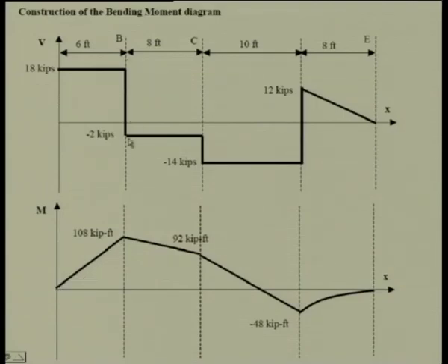Then suddenly it goes down, it is minus 2 kips. So, as you can see here, it is the sum total. So, it will keep going down after that. Once it reaches the maximum here, you are putting the moments, you are actually summing it up, but the moment it crosses here, the force has dropped to minus 2 kips. So, beyond that the bending moment will start reducing, as you can see it keeps reducing, and once it comes here it becomes more negative, therefore, the bending moment should decrease even further, and in fact, the bending moment has gone negative here.